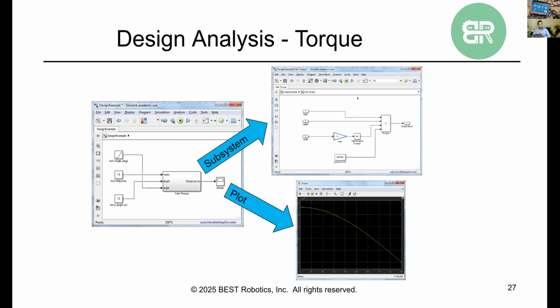One of the cool things is, like I mentioned, you can vary inputs and then see the outputs in real time. One of the most useful places to apply that is on your robot is measuring torque versus your arm angle and all of that, right? Because as you know, based on how far away your arm is, the distance, that sort of thing, it will affect torque. But that gets complicated to do by math by hand, right? It's a lot of trigonometry, that sort of thing. And in Simulink, you can have that immediately plotted as you move the motor around. So very, very valuable stuff for doing full on engineering design of your robot.